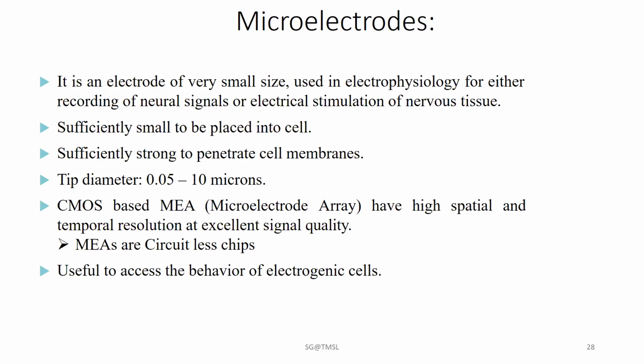Metal microelectrodes are constructed by electronically etching the tip of a fine tungsten or stainless steel wire to the desired size. Subsequently, the wire is coated almost to the tip with insulating material. Special electrolytic processing is also done on the tip to lower the impedance, and the ion metal interface happens at the point of contact between the metal tip and the electrolytes either inside or outside the cell.